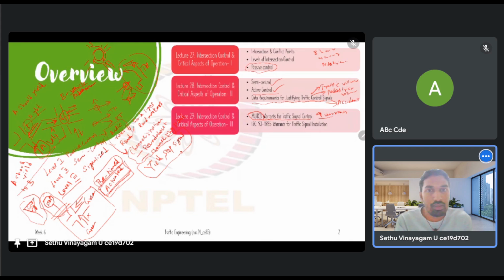Okay, it does not enforce this like a rule, but it suggests that we look into that particular intersection, whether it is suitable or not for a traffic signal. So if any condition is satisfied, we have to go for an engineering study, where we will be collecting all this different data and then look at whether we can reduce the accidents or the delays by installing the traffic signal there, right? So those are the warrants.